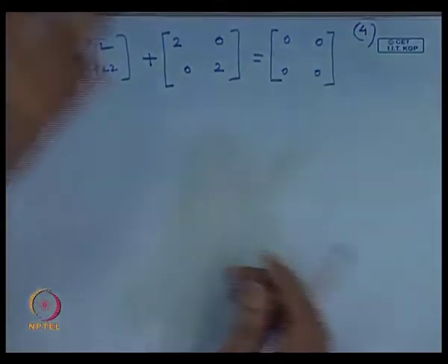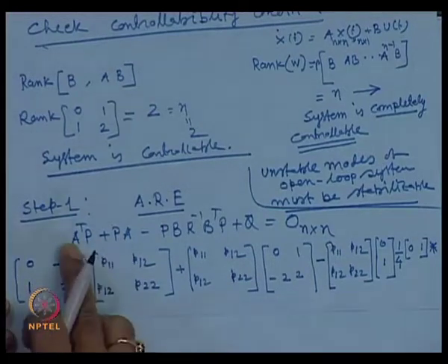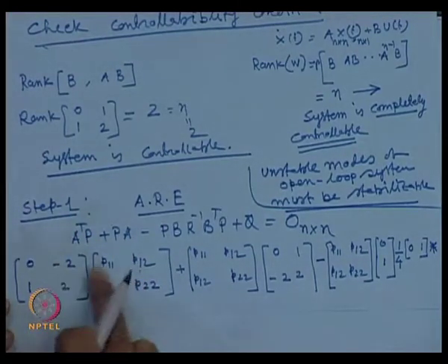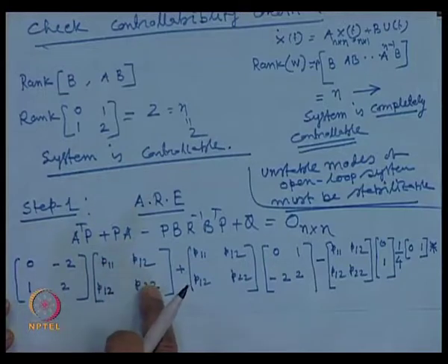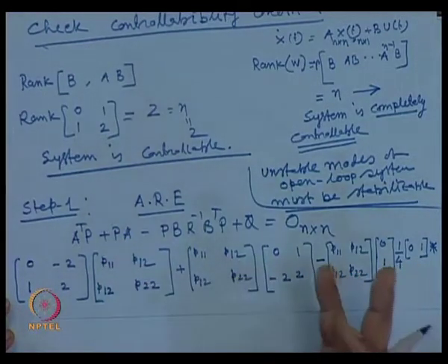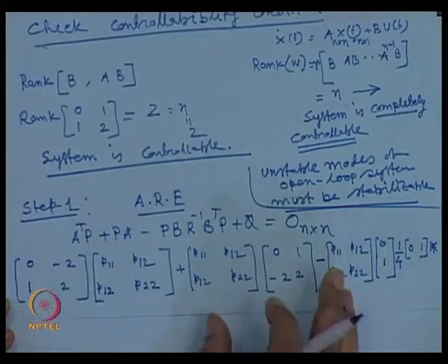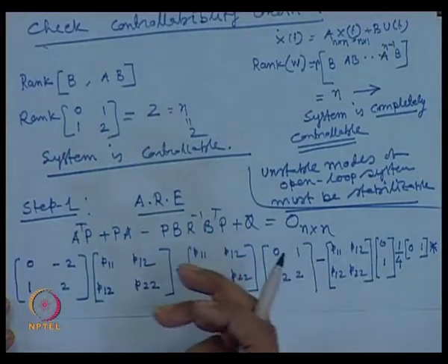And the right hand side is equal to 0 0 0 0. Okay. Now you see, multiplying A transpose P, there are 3 unknowns and we are getting at least 3 equations, so we will be able to solve. But when you equate the left hand side to the right hand side, you will get, in general, a nonlinear algebraic Riccati equation. Agree that we have to solve it.